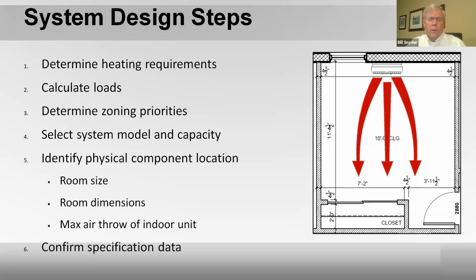It's really critical that we size this correctly, especially on the MXZs, because when one unit's running and heating, a little liquid will trickle into the other units, and we don't want to be overshooting the temperature. So it's very, very important that the unit be sized correctly. You get longer run times and remove more humidity. So that's a real plus.